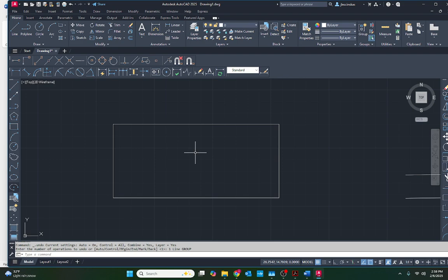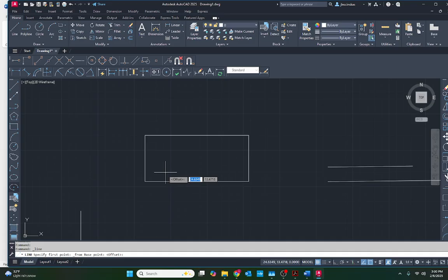This is where I want to offset my line from. At this point, you have to use relative dimensioning. This is why I suggest you use it everywhere when you're typing. If I type @1,1, I can start the line at a known offset point from that box.